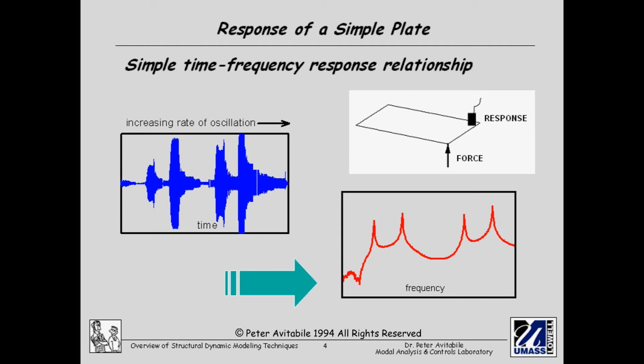Now this is very useful information because these peaks correspond to the natural frequencies of this structural system. So at any time we excite the structure at one of these resonances, we will get large response. Now one measurement shows me a lot of information, but I'm still missing some information because I only know how one point moves and I don't know what the rest of the structure is doing.